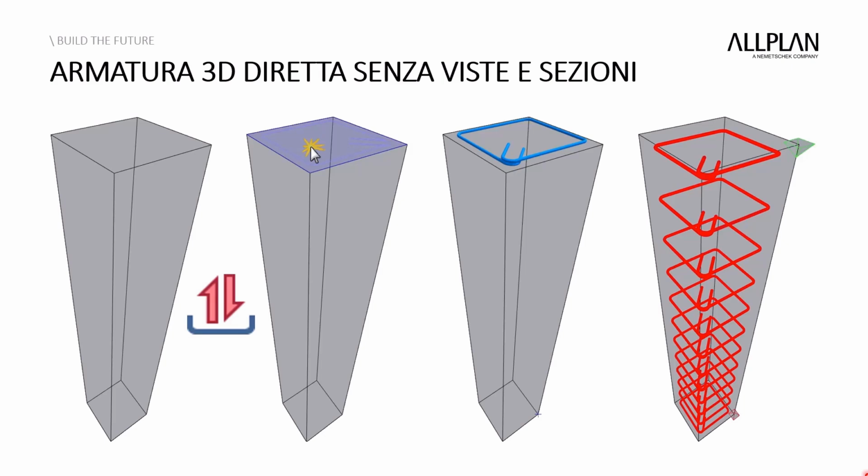To reinforce my model, I usually generate a series of views and sections of it. Then I go on to reinforce the views and sections to obtain the 3D reinforcement. Starting from the 2026 version of Allplan, I could potentially use a completely opposite workflow.